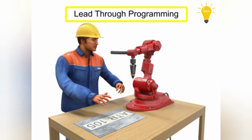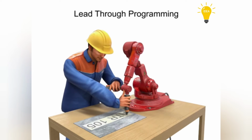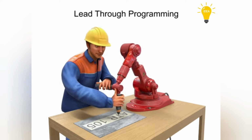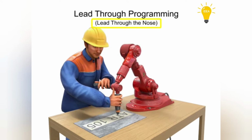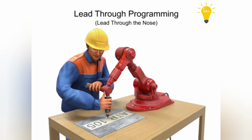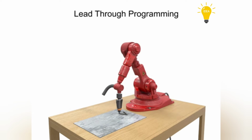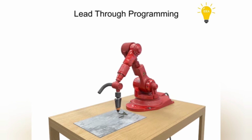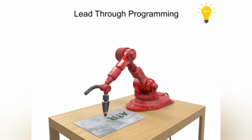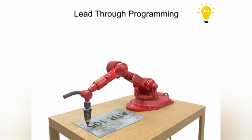Lead-through programming, which is typically associated with continuous path control, is a method by which the technician physically guides the robot through the desired program. This method, also called lead-through-the-nose programming, is used most often in spray paint and welding applications. It requires very little programming skills and allows experienced technicians to accomplish the work using the robot while the controller records each step. This method typically takes less time to accomplish than teach pendant programming.